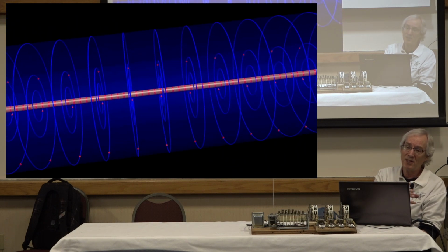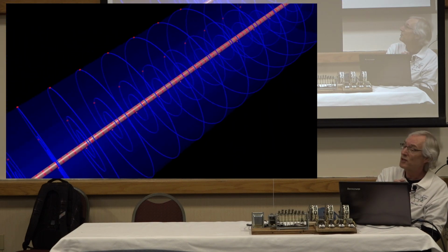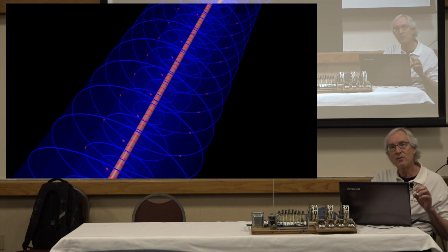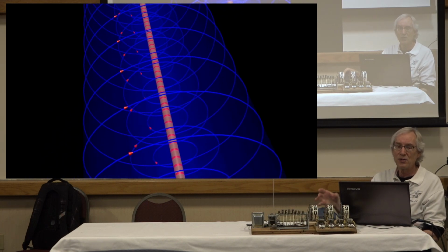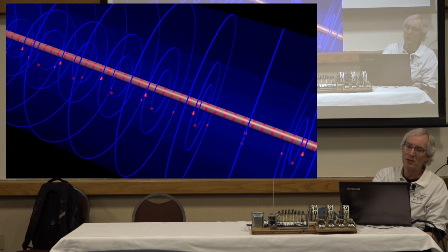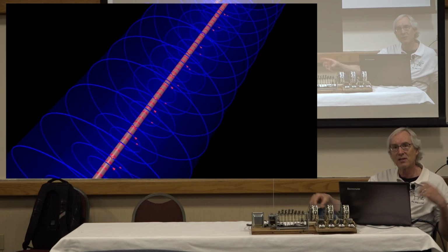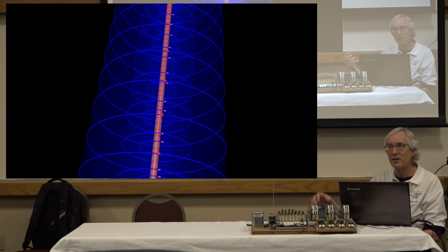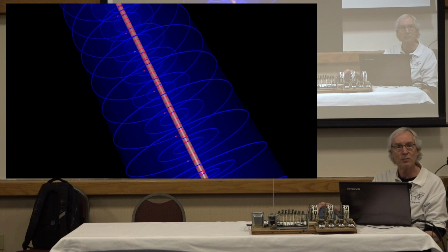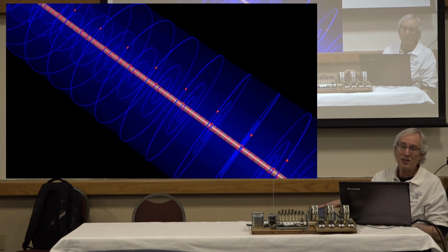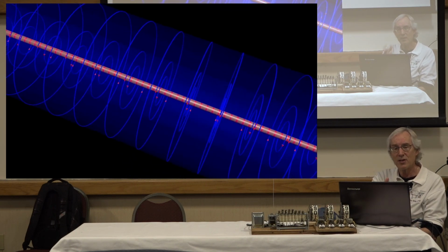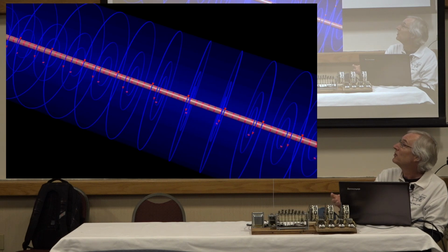The problem with this is that, as cool as it is, there's no way to control this. It's uniform across the length of that wire, so there's no way to attract a plunger or an armature to one section over another section. It's consistent across the length of that wire, and it's also very weak. There's not enough magnetic field here to really work with. But it's a first step, right? It's a way that I can create a magnetic field and have it under my control. If I stop that current, the magnetic field disappears.